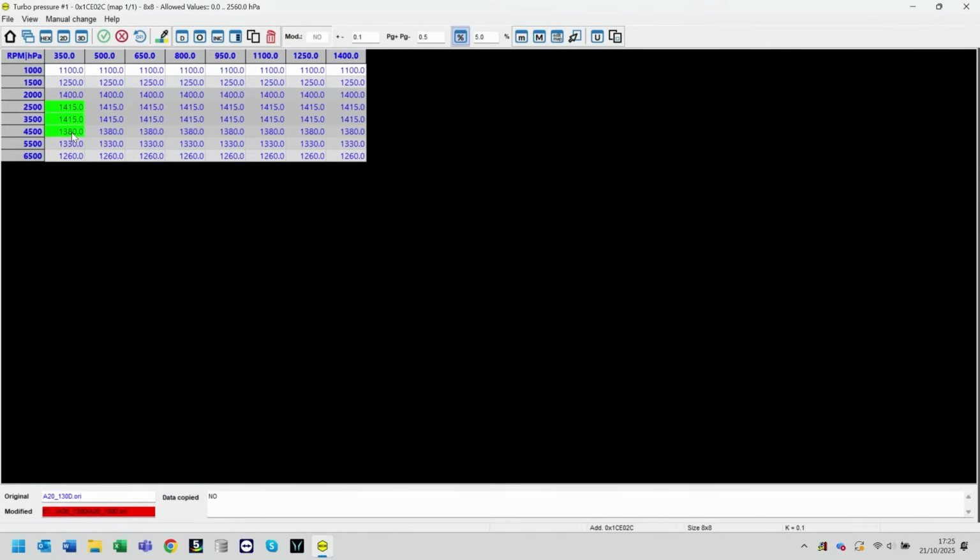If we're looking at taking our car up to maybe 190% of air, we just did the maths. That works out to about 1.3 bar, or 1,300 millibar. Well, we have an HPA turbo pressure map in here that's calibrated to 1,400 to 1,380 at that point. So again, we can see that the ECU is supporting these higher values, and there is even potential to push further if we started to move more into the high-end stage 1, stage 2 area, if we wanted to start pushing a little bit beyond the edge of those maps.